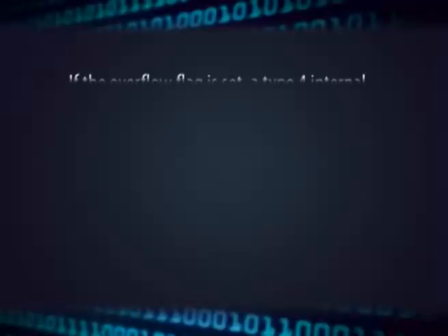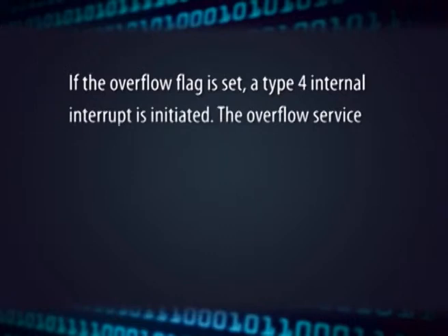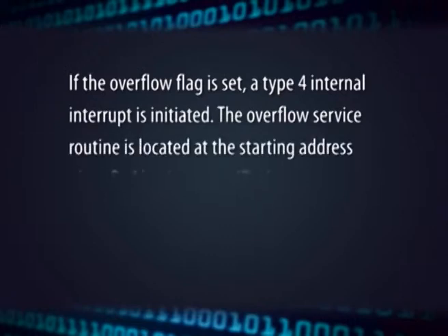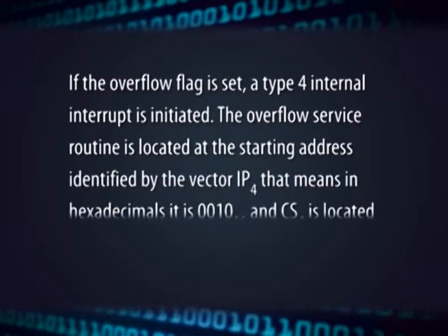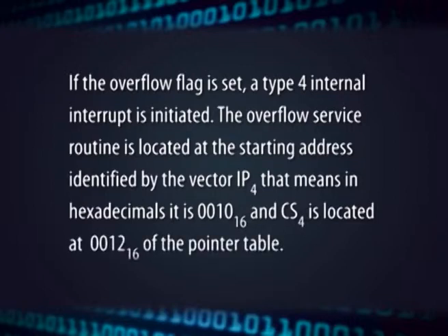If the overflow flag is set, a type 4 internal interrupt is initiated. The overflow service routine is located at the starting address identified by the vector IP4, that means in hexadecimal it is 0010, and CS4 is located at 0012 in hexadecimal of the pointer table.